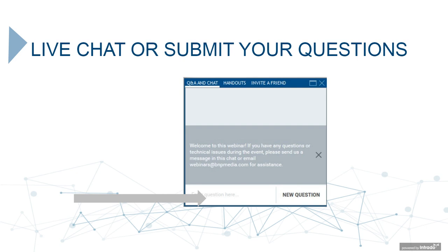Yeah, that's a really good question, and that pulls upon things that I talked about, and also what Sean was talking about, where Sean was showing those noise shielding wiring ducts. If you do use multiple layers or levels of shielding, they will actually provide you additional protection or additional noise reduction.